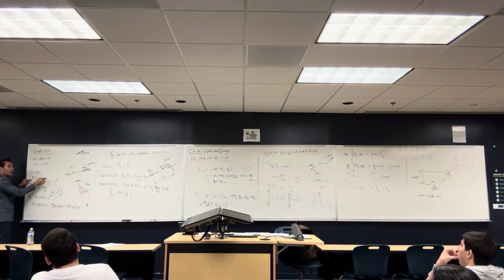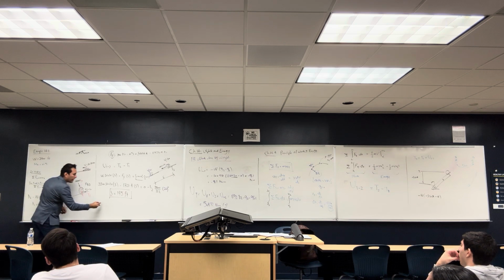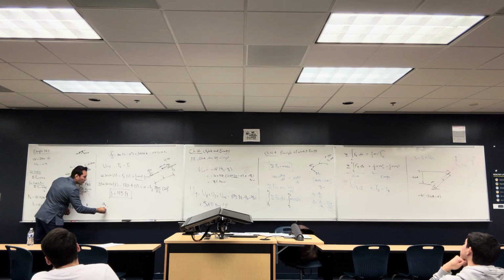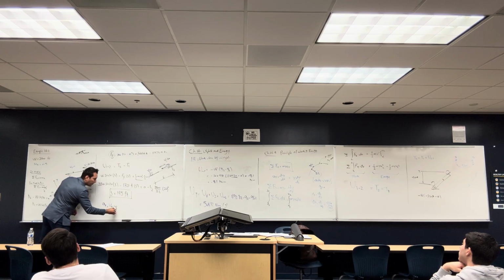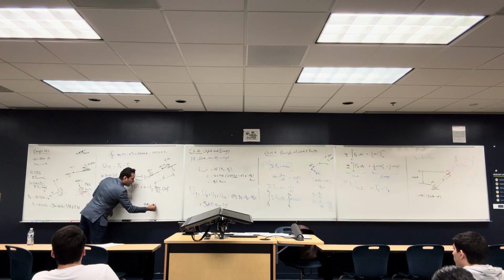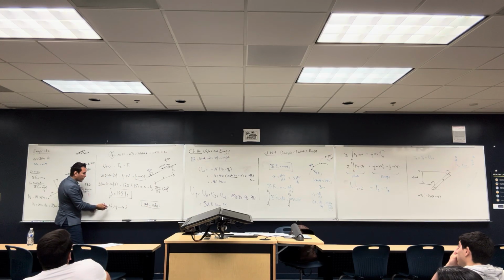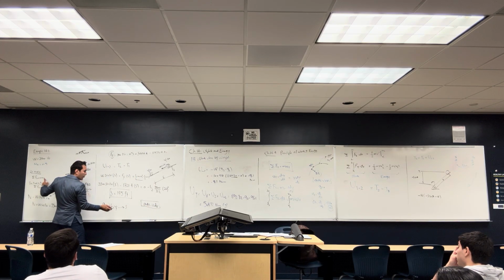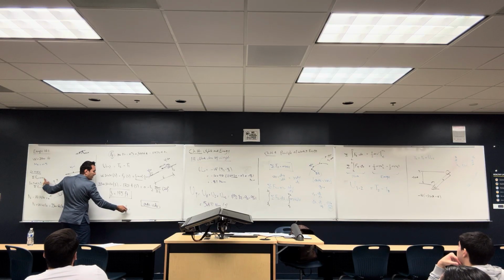It's going to be a function in ax, and if you find ax, and you also have the velocities, v node and v final, you can use these to get s from this equation. You remember a ds is equal to v dv. You already got a from this equation. You already know the velocities, the final and the initial one, and you want to get s.